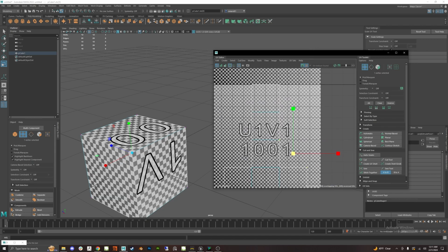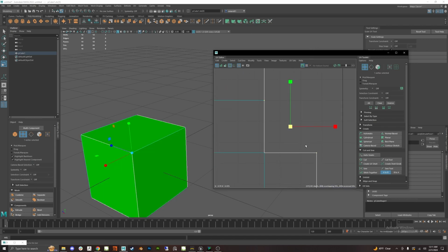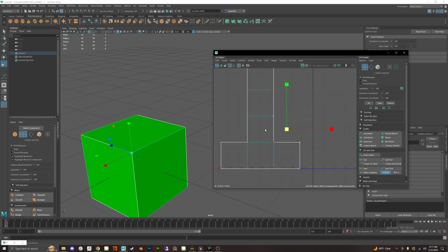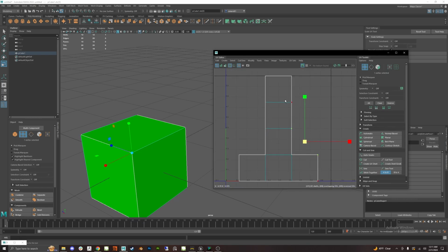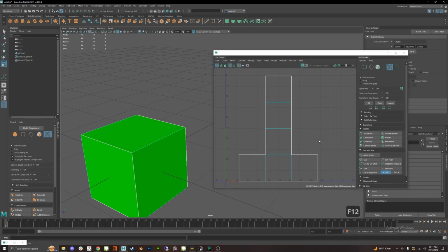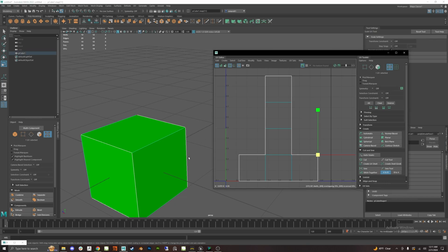If you notice, the highlighted vertice is collecting 2 different vertices, because the UV editor, while it is showing the object on a rendered 2D space, the vertice you have selected is a duplicate. So these are 2 different vertices, but on the 3D object, they're the same vertice. So that's why we have F12, so that we can highlight a quote-unquote vertice, and only have the one selected that is actually selected.